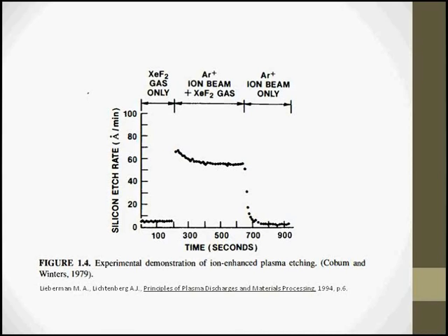But this is what we want to reel in. We need to control this. This type of high etch rate can over-etch these fine structures with single layer precision that we're trying to perform here with ALE. So in order to do that, we need to avoid or minimize the degree that we have the combined ion bombardment and chemical etching.